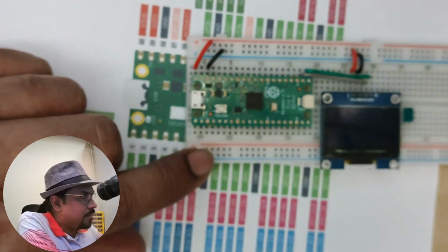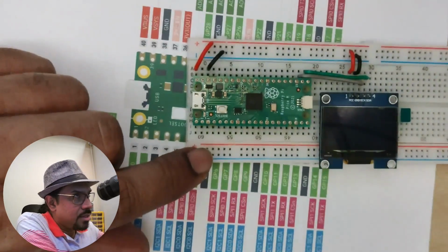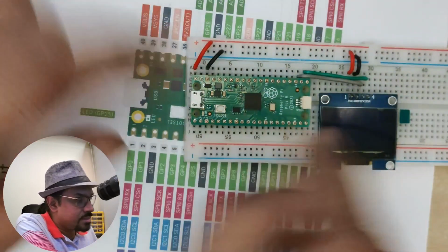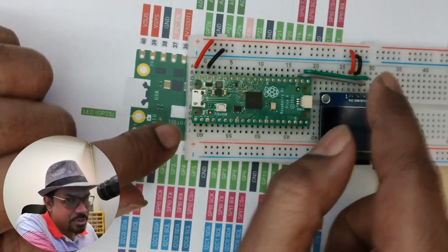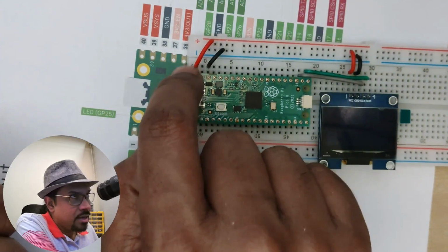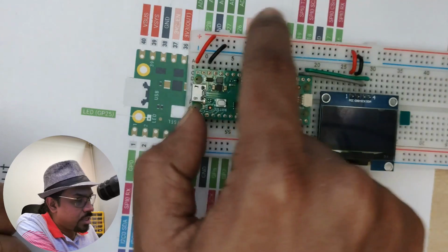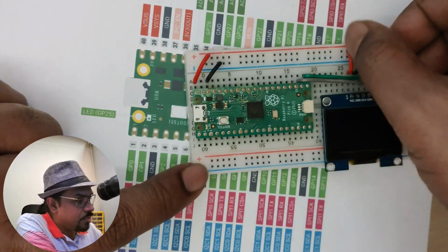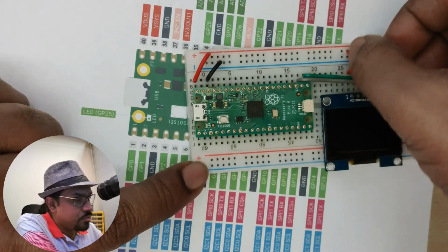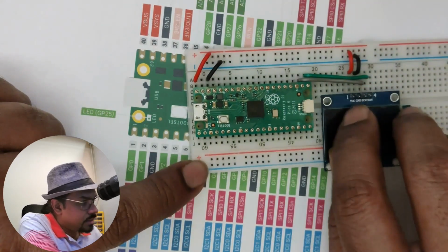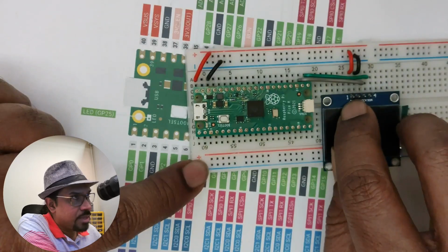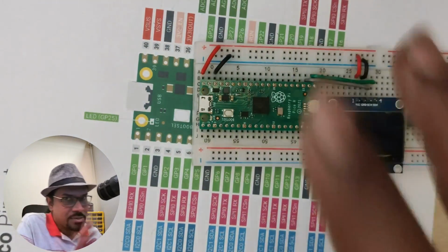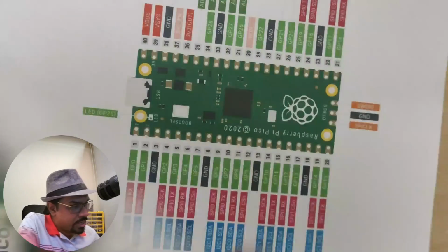So anyways, here, same thing. I've just made the connection in here exactly identical to the previous one. Only thing is the VCC and ground is interchanged, right? You can see that the VCC pin from the Raspberry Pi Pico, which is pin 40, runs across a positive rail. The positive rail is on top this time on this breadboard. It goes to this red wire that is there here. This connects to the VCC pin in the side. Let me just make sure that I don't have a problem with parallax because it's on the side. I'm just going to ensure that it's all correct.